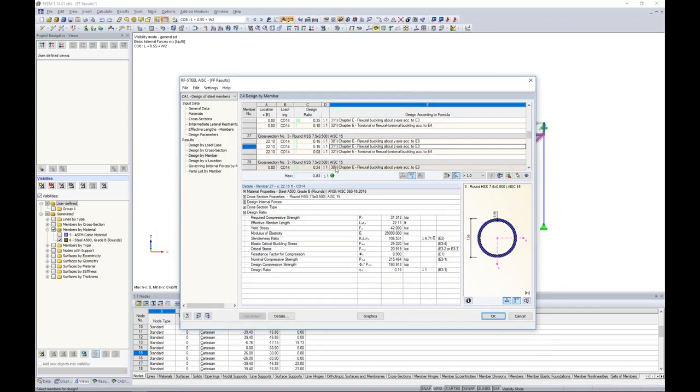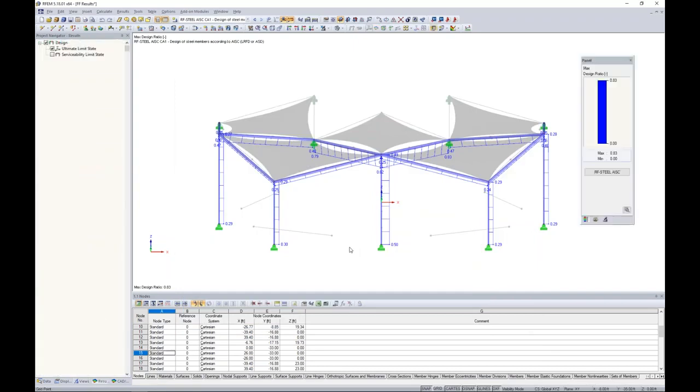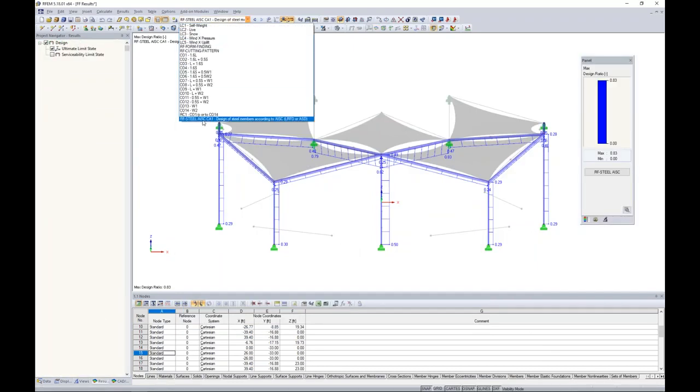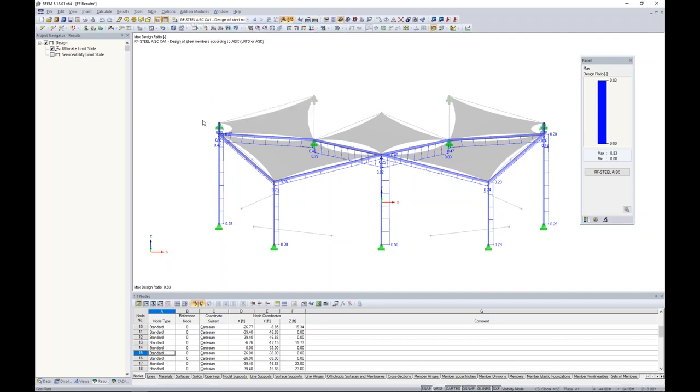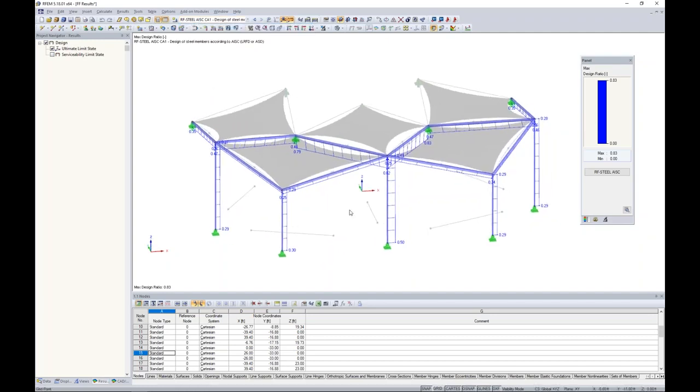We're getting a design here for our HSS members of 0.83, which I would say is pretty great for design purposes. We can view this information graphically back in RFEM, so we're technically still within this steel AISC module, but we're viewing our results graphically here back in RFEM. So again, I know a really quick explanation, but again, refer to those previous webinars that I have created.